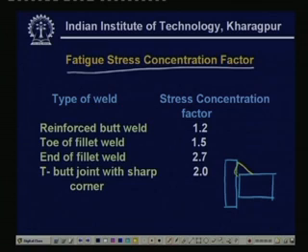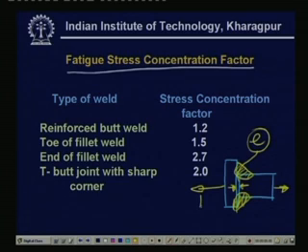Suppose we have this fillet here. Now, you see, when we want to make two fillets here, then definitely there will be a gap that cannot be avoided because of some error. So, this gap E, if you consider the loading, that is, if you consider the real joint, is nothing but a crack. Therefore, a stress concentration will exist over here. So, there is a large stress concentration here. There are various other possibilities of stress concentrations.